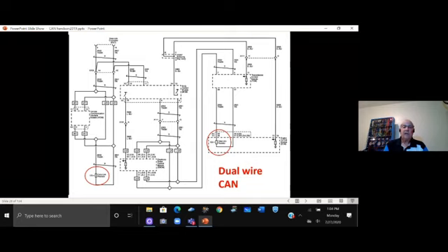How is it added? It's added very easily. We give the person a new key fob. We reprogram the key fob module or vehicle communication module, and we connect that module to the CAN bus. Bingo. We just put auto start on.